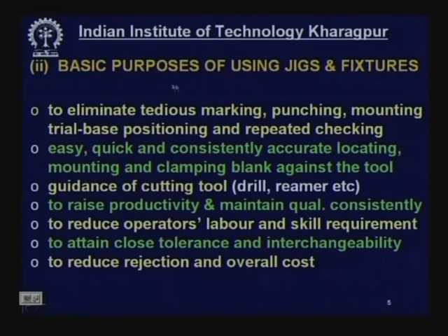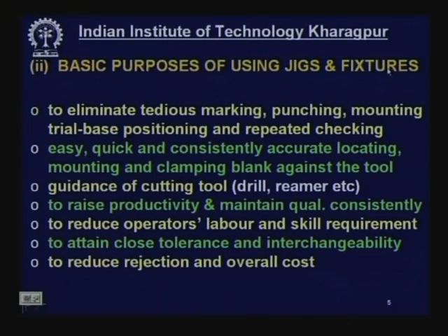the basic purposes of using jigs and fixtures. Now, first of all, to eliminate those tedious activities like marking, punching, mounting, trial based positioning of the vise or job, and repeated checking, measurement, this tedious time consuming work has to be eliminated, and that can be done by use of jigs and fixtures.